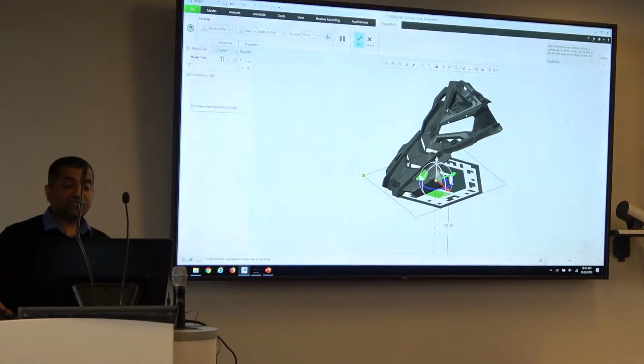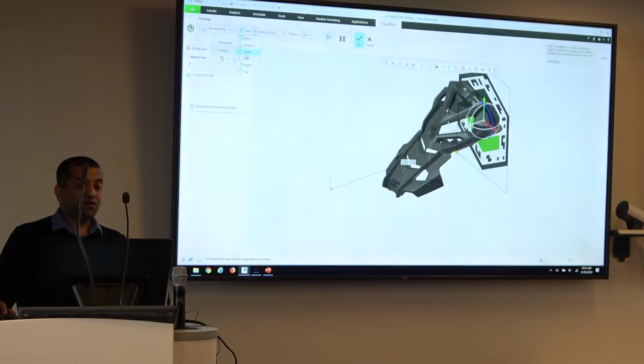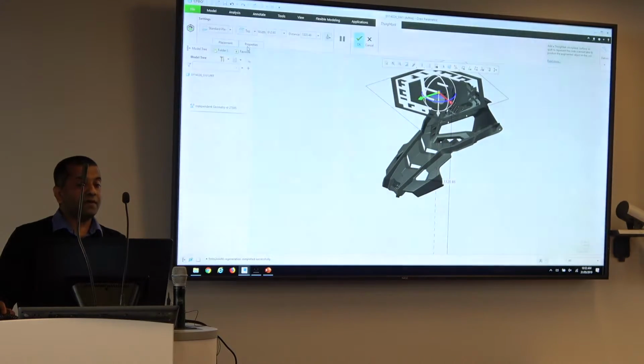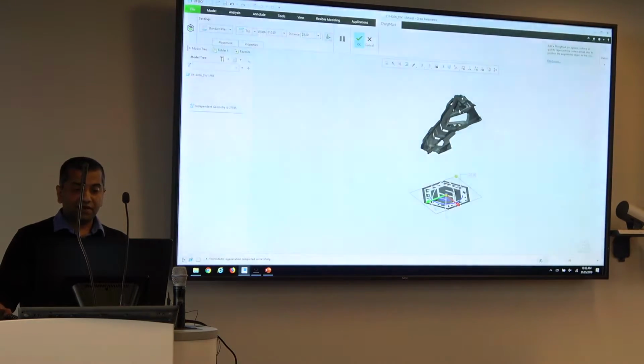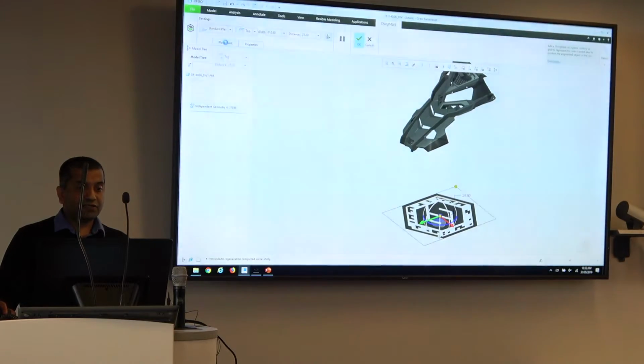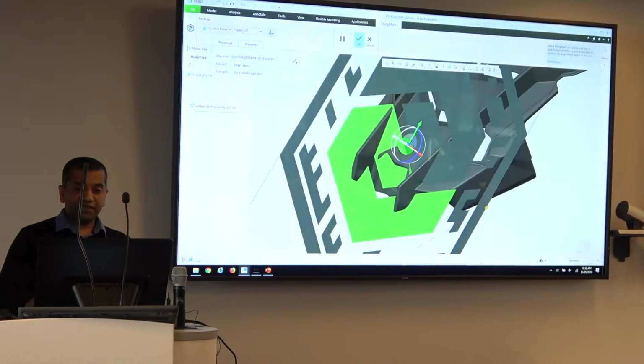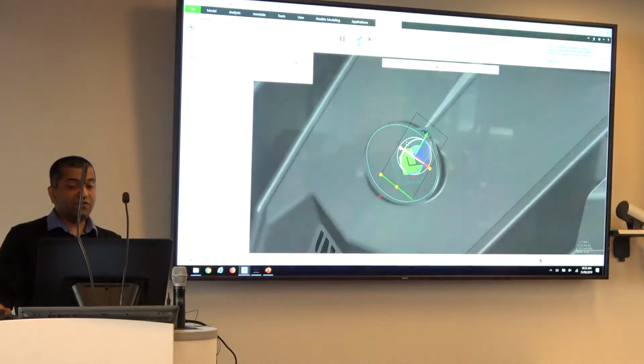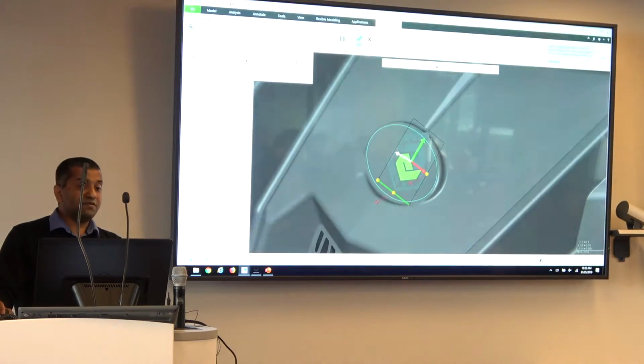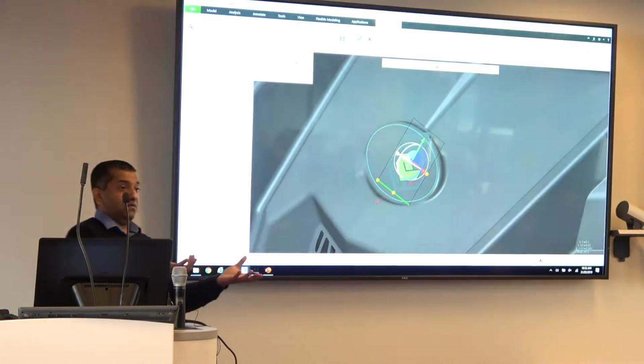So when you place this ThingMark here, you can put some default orientations, like a back view or a left view or front view or something like that. You also have a custom placement here. You can go and place it custom. You can also change the scale. For example, I can set it to a small size here. Then I can go and place it on a custom plane. Like I can select a surface here, and maybe I can change the width here to a really small size. Then we can also accurately position with some references here, same like we place a hole on an axis.